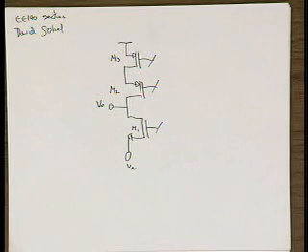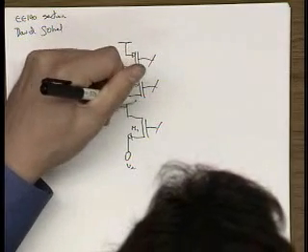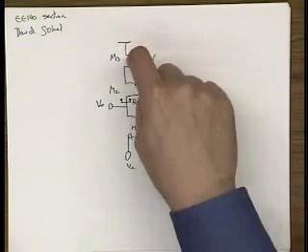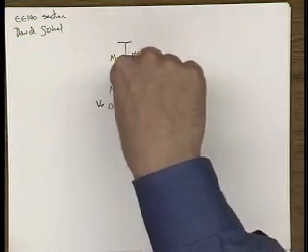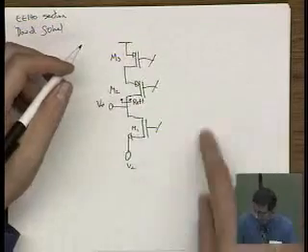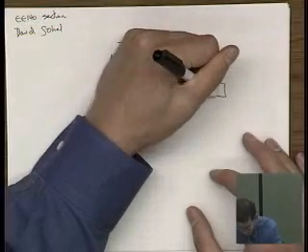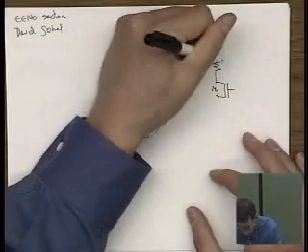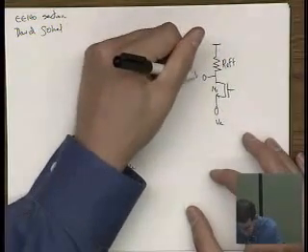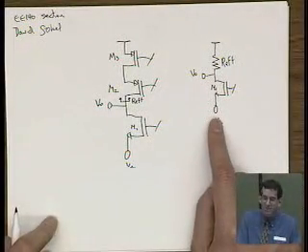Yeah? Change that to a resistor on top. Exactly. So looking up here, we can say this is an effective resistor, M2 degenerated by M3, right? The basic goal is that once we replace this with a resistor, then what it looks like is a single transistor amplifier, M1, R effective, VI, V out. And this is easy. Okay, this is less difficult.